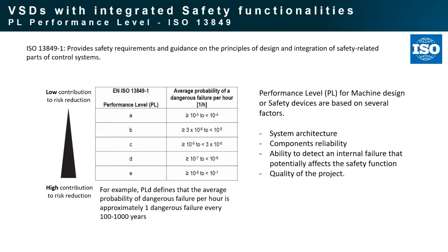The performance level for machine design or safety devices is based on several factors. For example, the system architecture: how the components are installed, or what the architecture, the design of the complete machine is. It will also evaluate all the components' reliability, the ability to detect a failure that potentially affects the safety function, and also the quality of the project itself. And so this standard will not only define how to classify, but especially how to design the machine in a safe way.